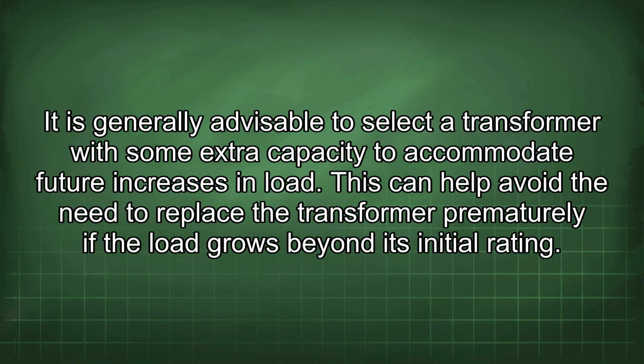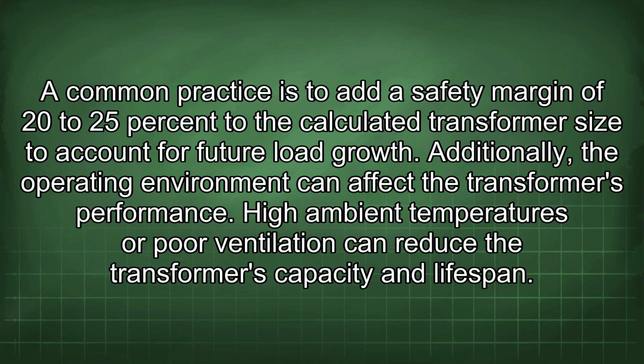It is generally advisable to select a transformer with some extra capacity to accommodate future increases in load. This can help avoid the need to replace the transformer prematurely if the load grows beyond its initial rating. A common practice is to add a safety margin of 20 to 25% to the calculated transformer size to account for future load growth. Additionally, the operating environment can affect the transformer's performance.